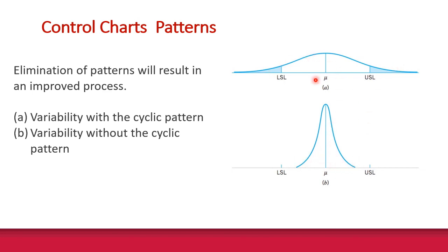So which one of these would you prefer, if you were manufacturing product, A or B here? This one, you've got some problems here, right? Falling out, you're manufacturing products here that are outside of the spec line, so obviously that's a problem. Theoretically, you'd want it to be as centered as possible, and the variance to be very, very tight here, right? You want some room for error here, right? So if the process shifts just a little bit, you'll still be within control here. So ideally, you want this very narrow.